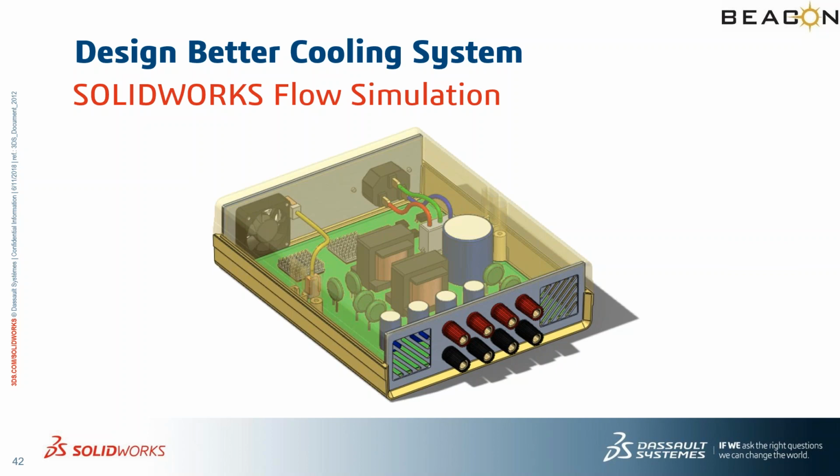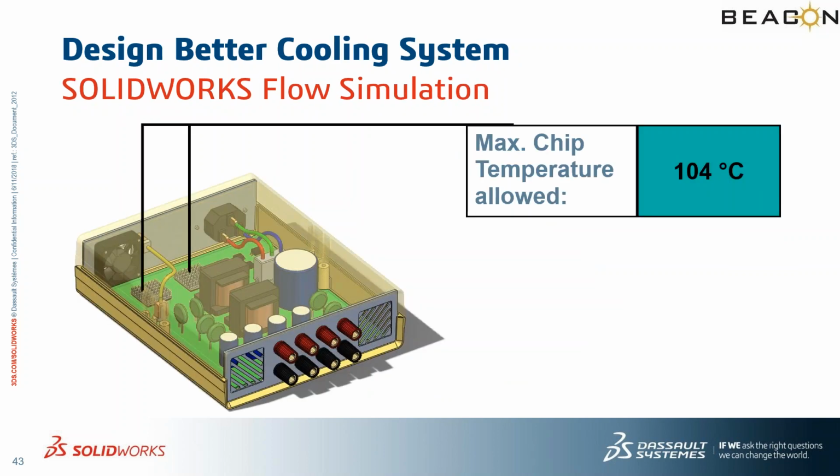For the product demonstration, for this example, I have a requirement saying that there is a chip and the maximum chip temperature allowed is 104 degrees centigrade. So anything more than that is not allowable for me in this design. So now I wanted to make sure that the temperature of the chip is not going beyond 104 degrees centigrade. To make sure that my temperature inside the chip is not going beyond the limit, I have several conditions to work before.